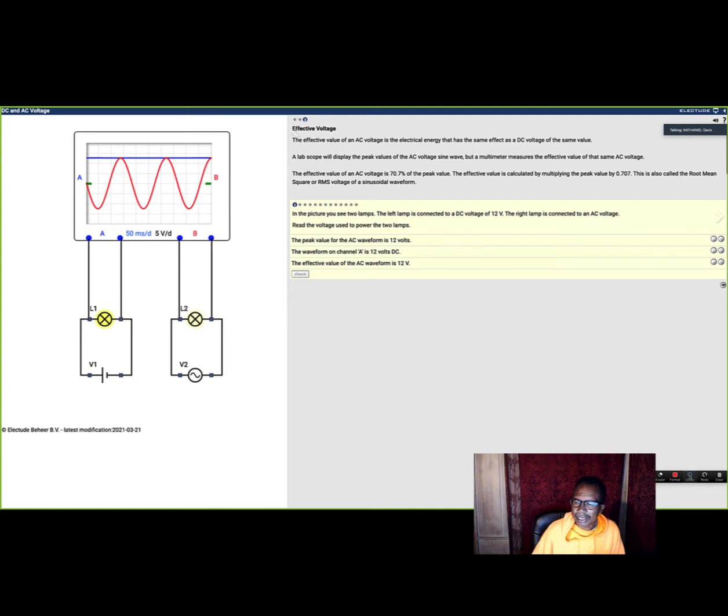Now look at this. Before it was 2 volts per division. Now it's 5 volts per division. So each division, which is a square block, is 5, 10, 15. And you can see that's right somewhere in the middle. That's how you got to 12.